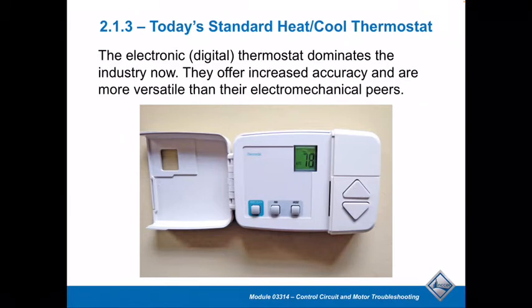If you have the ability to, and all the thermostats are going to have this, they'll have what they call a dead band within the thermostat on an auto changeover thermostat, and that could be anywhere from 2 to 3 degrees as a general rule.